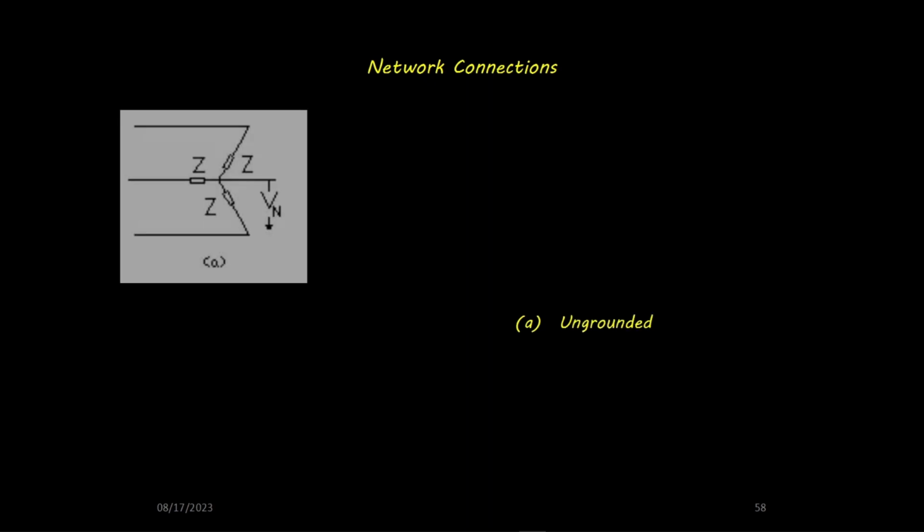In an ungrounded Wye, equipment is connected with one lead connected to the phase and the other lead connected to a common point, usually called the neutral. There is no connection from the neutral to the ground. If the equipment is a load, then there is no ground path back to the source. There can be a voltage between neutral and ground in unbalanced systems.